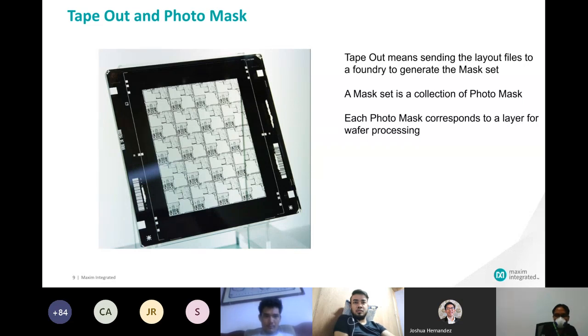In the 90s, usually when we create those business models, we say that the cost to design, the cost to do the layout, the cost to do the simulation, the cost to do the full mask set, and the cost to fabricate the first set of wafers, that costs about $1 million on a 6-inch wafer process with a 1 micrometer process node technology.